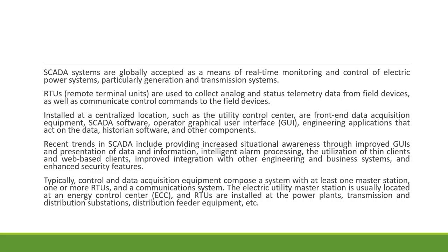These are installed at a centralized location such as the utility control center, and our front-end data acquisition equipment, SCADA software, operator graphical user interface, GUI, which is commonly known as engineering application, which acts on data, historian software and other control. So we are talking about the equipment installed at a centralized location, which are front-end data acquisition equipment, and the SCADA software operator will be included in that.